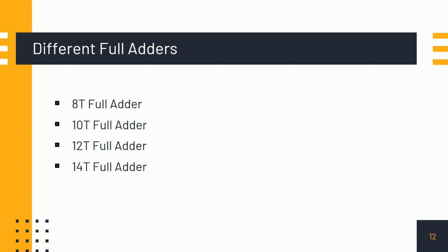At first, we designed the schematic diagram, then we generated the layouts of the circuit using Layout XL. Then we ran DRC to ensure all the design rules are maintained. Then we compared the layout with the schematic design to make sure all the parameters and pins are matched.